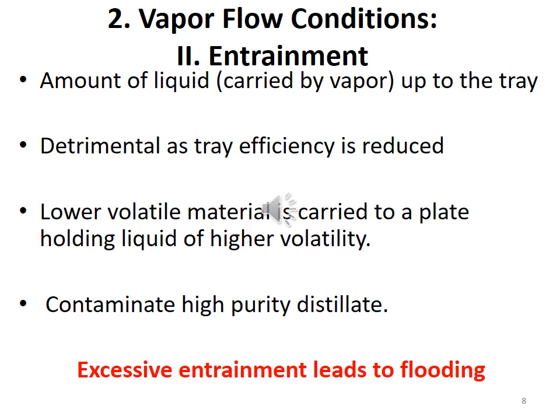Therefore, the process of entrainment could lead to the contamination of high purity distillate. So precautions must be taken to reduce this effect of entrainment, which can lead to the flooding.